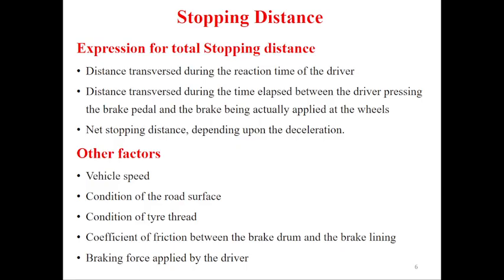Now the stopping distance. The expression for the stopping distance is the distance traveled during the reaction time of the driver, plus the distance traveled during the time elapsed between the driver pressing the brake pedal and the brake being fully applied to the wheels. The net stopping distance depends upon the deceleration.